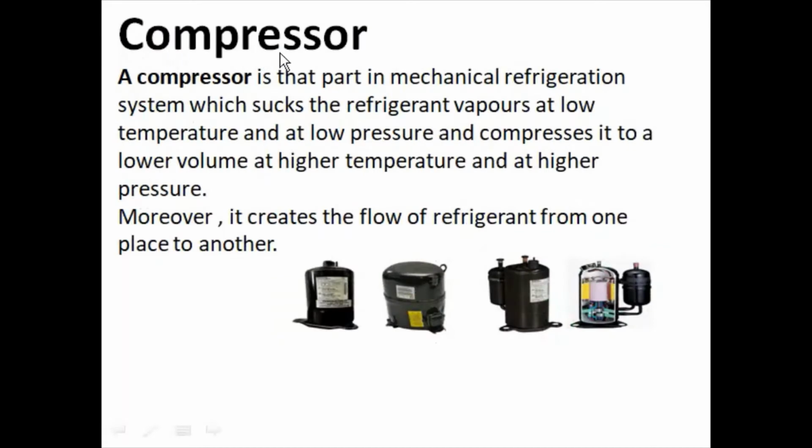Starting from the compressor. By its definition, the compressor is that part in the mechanical refrigeration system which sucks the refrigerant vapor at low temperature and low pressure and compresses it to a lower volume at high temperature and high pressure. Moreover, it creates the flow of refrigerant from one place to another.